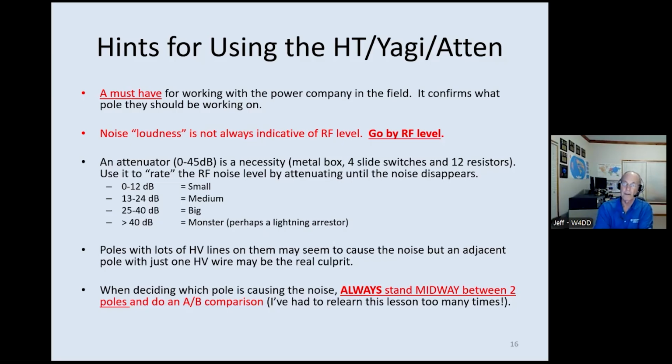So some hints that I've learned over the years, and basically I call them bunny trails I've traveled down and been trapped on and made a mistake and had to go back and redo some measurements or something. I find that the HT system with the Yagi and attenuator is really a must-have if you're going to work with a power company. You want something where they hear the noise too, because that's going to motivate them like, hey, yeah, this is a problem. And as soon as they touch something, they'll hear that change. I usually turn the speaker up so they can hear it too. And they go, oh, I just touched something and the noise went away. So it can be a very useful tool.